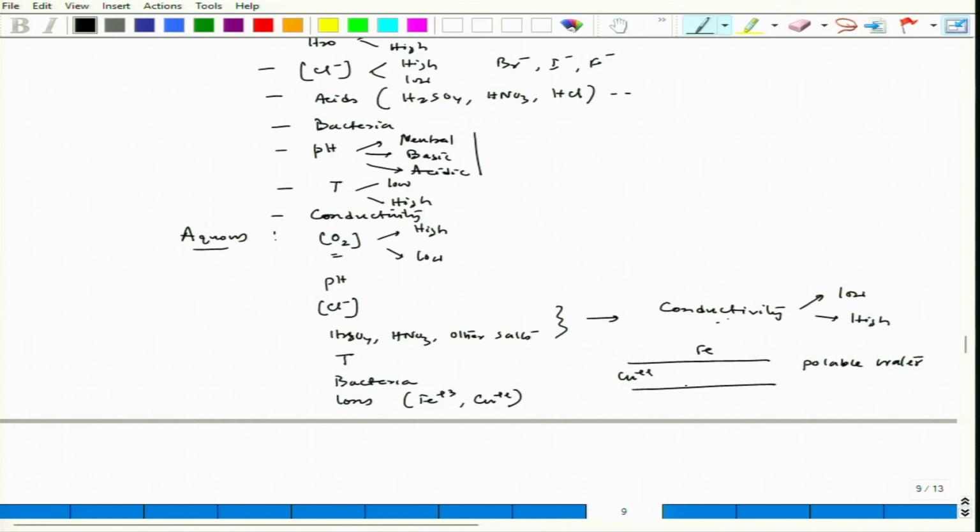Now, there could be a possibility of copper deposit, because with 2 electrons it can deposit. Once it deposits, at that deposition point, since copper is above iron in the galvanic series, the copper part would act as cathode.